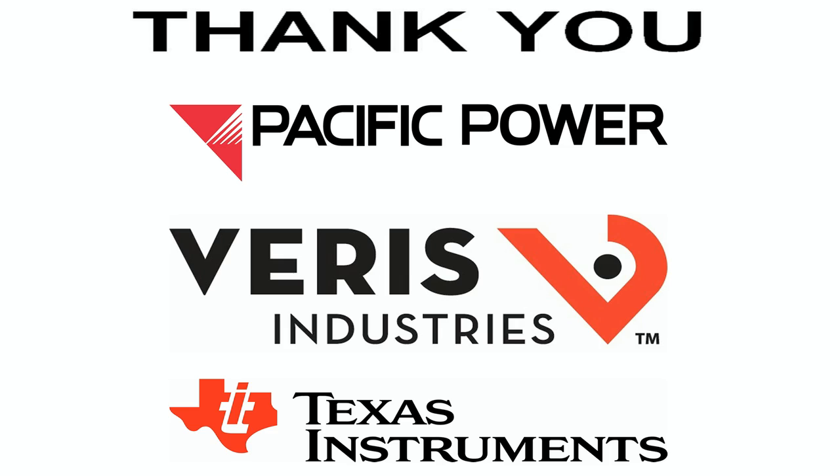One tip I'd have is if you're going to design a PCB for your project, make sure you put test points and LEDs wherever you can on the board. This will help diagnose any problems that you might have with the circuits if they're not quite working right. It'll just give you a better look at what's going on rather than being stuck maybe cutting traces on the board when you really don't need to do that. If you have the test points and LEDs, you'll be able to see the problems a lot clearer.